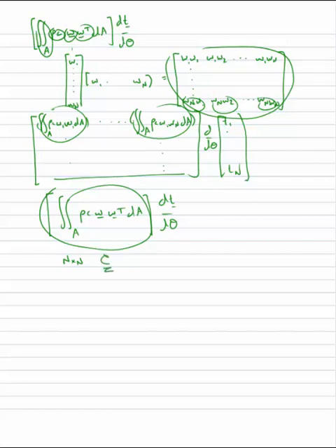So this is a capacitance matrix times dt d theta. The capacitance matrix for finite element looks a lot different than it did for finite differences, but it ends up being something related to the heat capacity, we'll see eventually. And if I knew what these weighting functions were, I could actually do these integrals and construct my capacitance matrix.